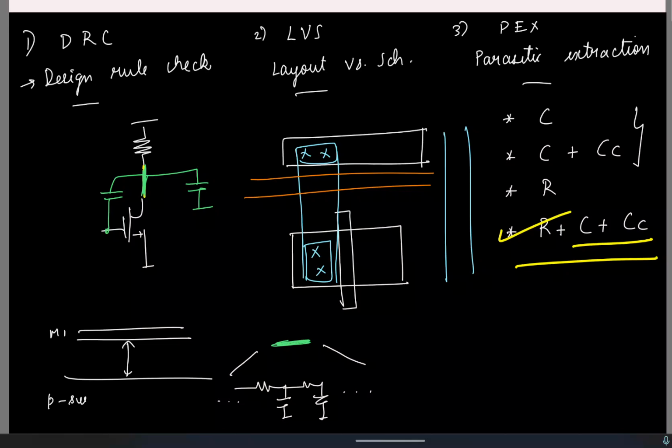But let us say you find that you can't tolerate any parasitic resistance in some path, then you do your layout accordingly. That's exactly why you should have some understanding of what the circuit is doing and what is more critical in your circuit. You cannot always rely on simulations, because the final simulations might run for several days. You can't change something and then check if it's working or not.